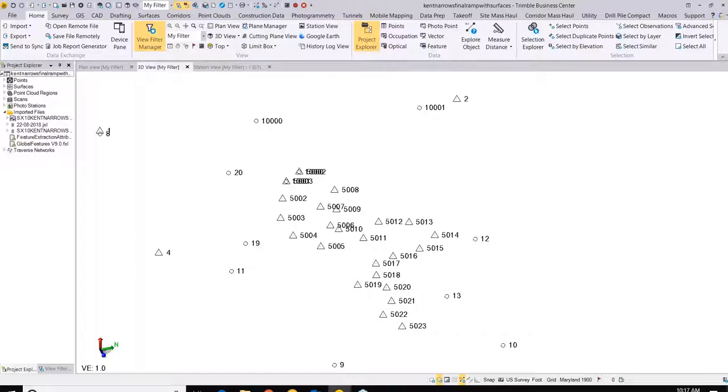So, yeah, just showing the points on that one. Like I said, that way you know where the top of the top water shot is from that. Also, speaking on that, if your mean low water depth to your NAVD 88 is within the 7/10 range, you can actually set that up on the Sonarmite. You can set that depth so that it's actually giving you a true depth right down in there if you're really good at doing that and know how you set those depths.